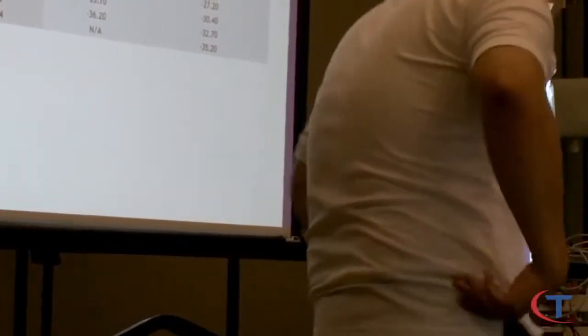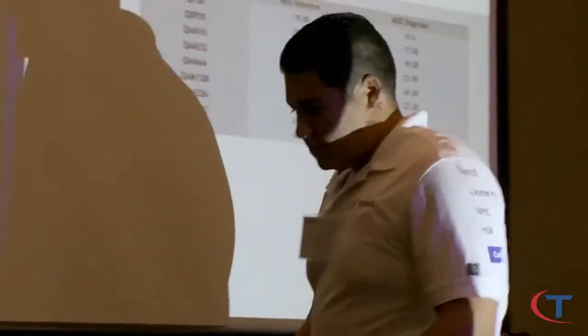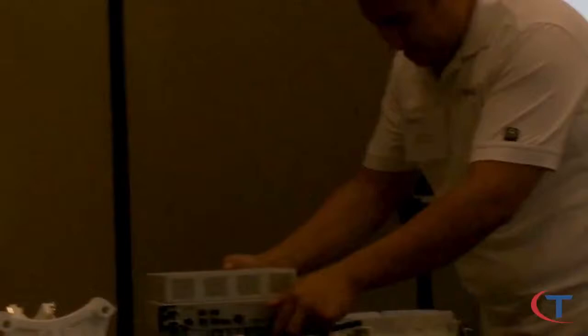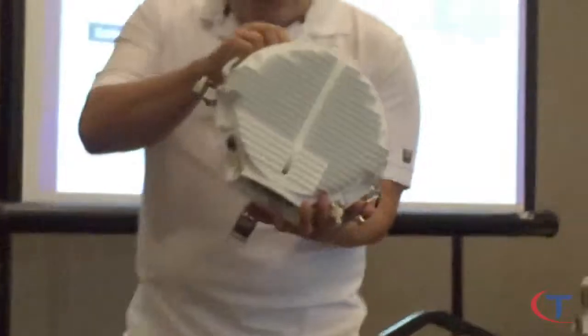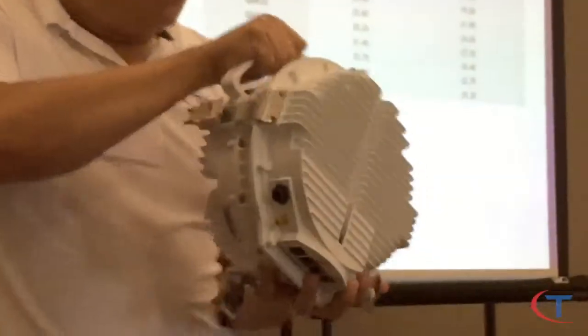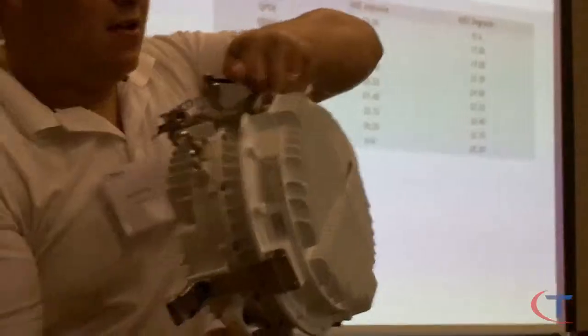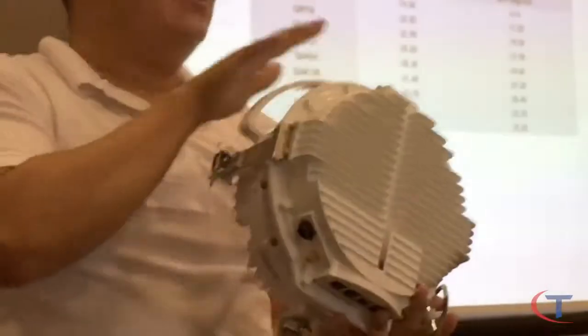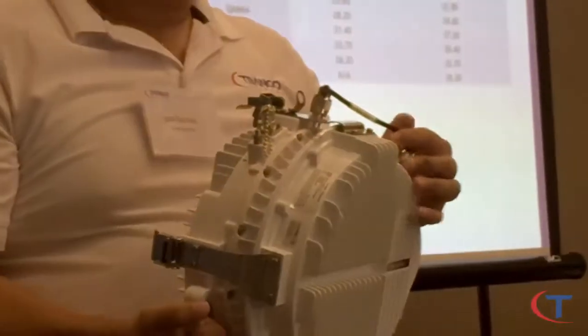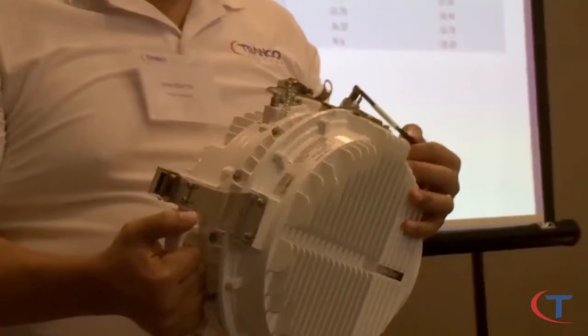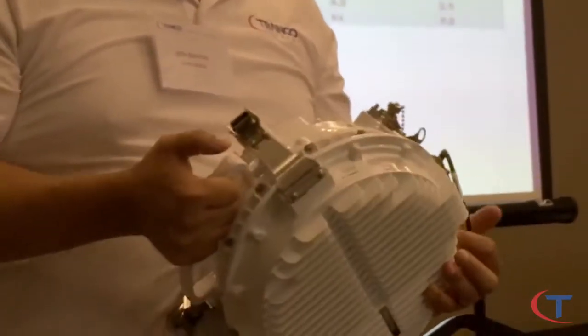I've seen cases where it happens, and good thing you brought it up, because I don't think I mentioned this before. This is called a carry handle. This is not a carry handle, okay? This is actually a carry handle. And it's funny, but I've seen this cable on RMAs be totally bent or stripped because the installer on the tower decided to grab it to move the antenna around. And this is actually an IF cable.